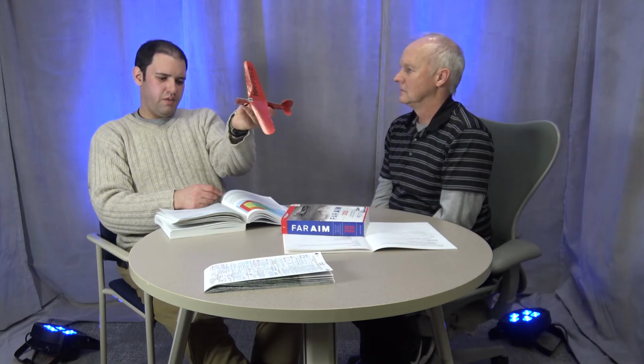We've talked about how as we have to create more lift due to the airplane changing direction, that creates more angle of attack to create more lift in order to help the airplane change direction, either pulling out if we're nose down, or if we want to pull up. If we're turning, we have to create more lift to change direction. And that feeling of being pulled down in your seat, we call that a G loading, G for gravity.